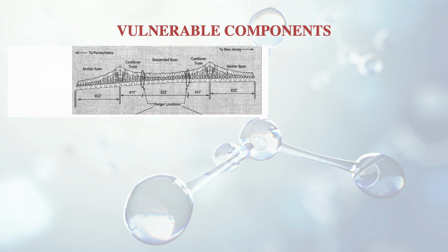Often these hanger pins undergo the process of corrosion which remains undetected. So this is a very critical phenomenon because it undermines the safety of the structure. So it's very important to monitor such components in the infrastructure.